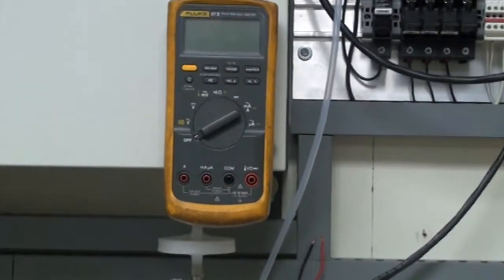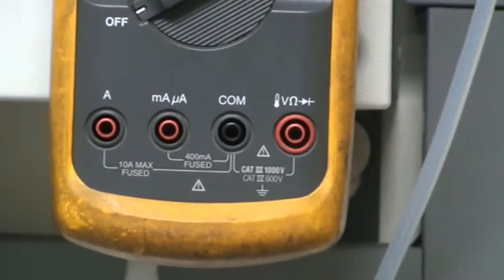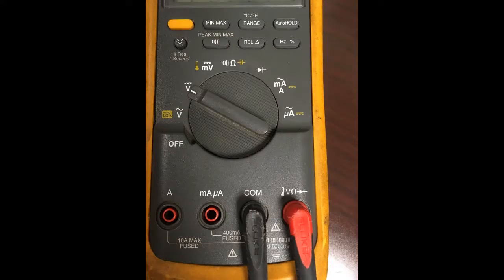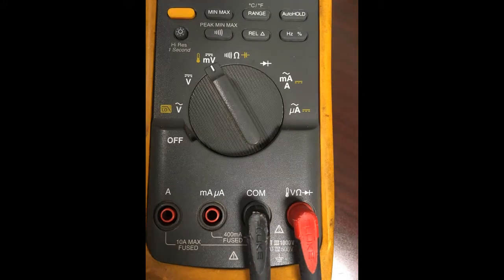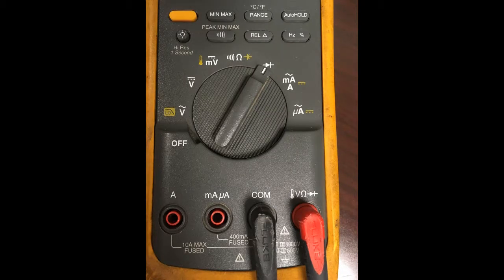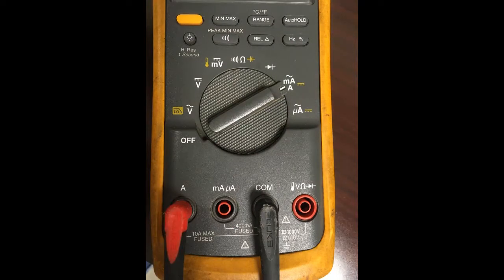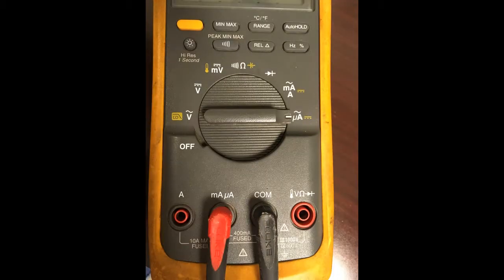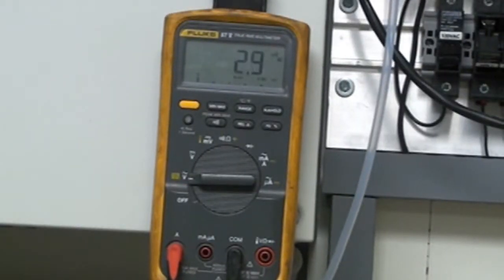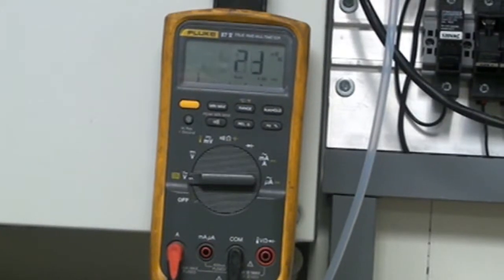Most digital multimeters will offer a variety of test lead connection ports. The white symbol above the test port will correlate to the dial selection legend. In the case of the FLUKE 87, the black test lead will always remain connected to the black port labeled COM, and the red lead will move to the port designated by this white symbol. If the meter is configured for current measurement, and the selection dial is set to anything besides current mode, an audible tone will warn, in addition to the word lead flashing on the display.